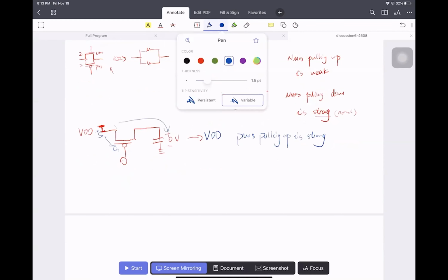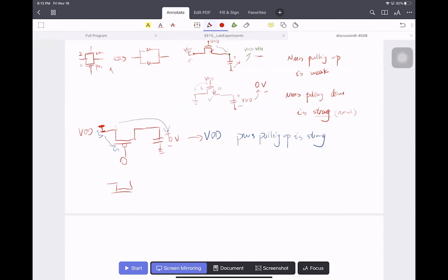But if you use PMOS to pull down, here is 0. The other is VDD. So what will the final voltage of the capacitor be? Here, this side is the source. This side is the drain. So gate-source is here. Basically, gate-source keeps decreasing until the output reaches VTH, so that this PMOS is in cutoff region. So at the end, the output can only be VTH.